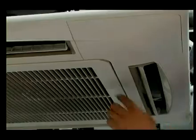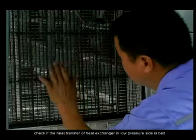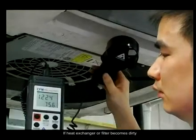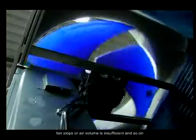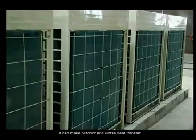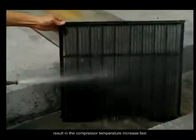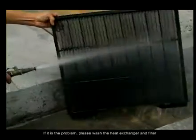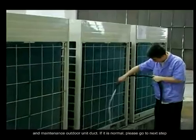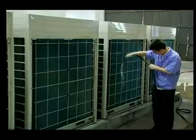Step 3. Check if the heat transfer or heat exchange in the low pressure side is bad. If the heat exchanger or filter becomes dirty, the fan stops, or air volume is insufficient, and so on, it can make outdoor unit heat transfer worse, and the working condition is terrible, resulting in the compressor temperature increasing fast. If it is the problem, please wash the heat exchanger and filter, and maintain the outdoor unit duct. If it is normal, please go to the next step.